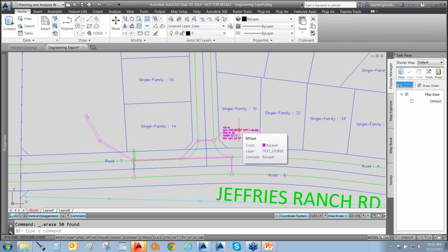So using a couple of AutoCAD tools. We're not using GIS fancy tools. We just use AutoCAD tools. Layer translator, layer isolate, delete layer, that kind of thing, purge layer. I'm managing to clean up my data, and this is just the stuff that I want to start throwing in.